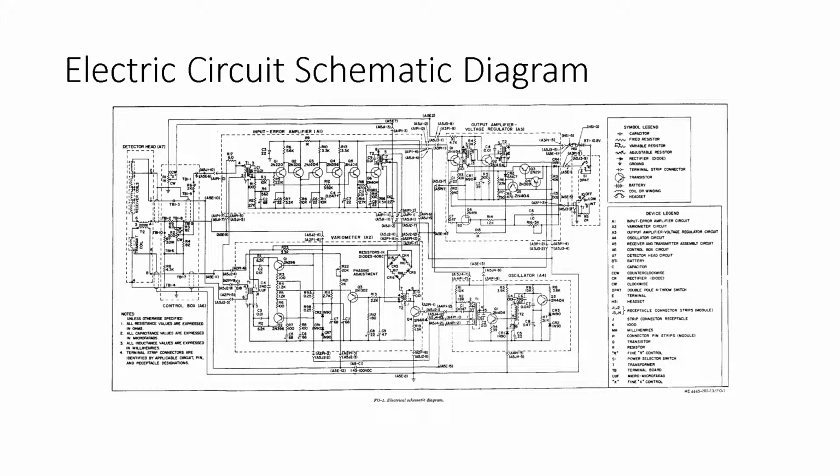On the top right hand side, we have a symbol legend, and these actually are very rarely included on most schematic diagrams. Most people know exactly what you're talking about because you're going to use essentially a common set of symbols. The only thing that we might put in the symbol legend is something that's very, very different. So if there's a part that we're not used to using, or if there is some kind of designation on there that says remove this part during testing or whatnot, sometimes it'll go in the notes, sometimes it'll go in the legend to be able to show what that part is.